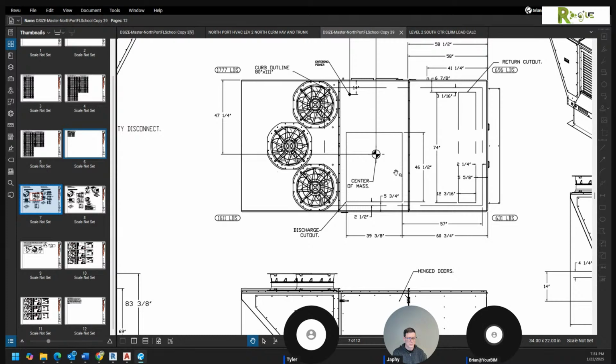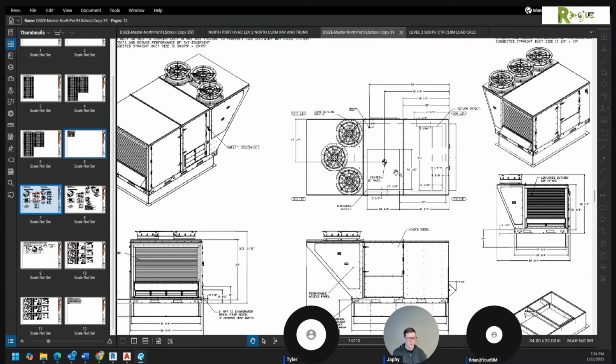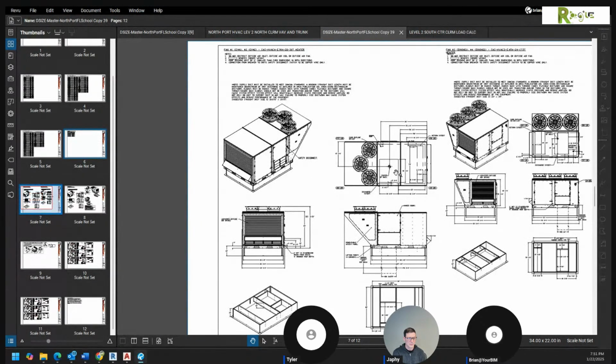And then once I make that, and here's the problem. He wanted me to stop on all this because he's realized that these submittals aren't accurate because these are for gas units and we don't have gas out there. We have electric. So the electric unit's going to have a different footprint. Well, guess what? According to the way I've done it, it doesn't matter if you have a different footprint. You just adjust the footprint and verify your duct connections. And that's something you have to do.